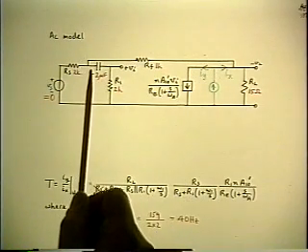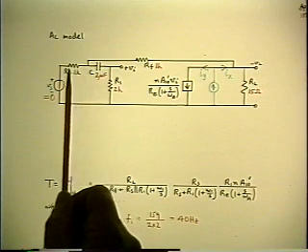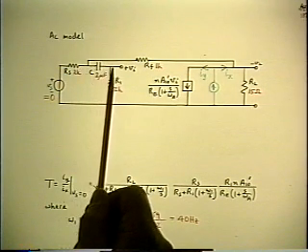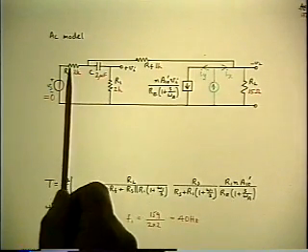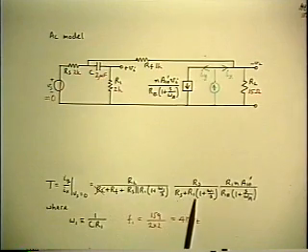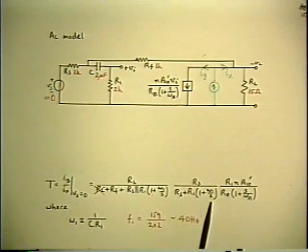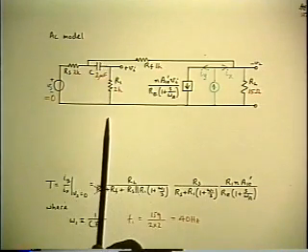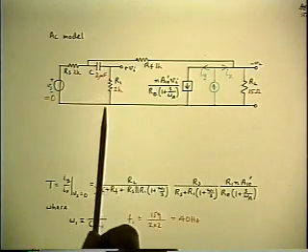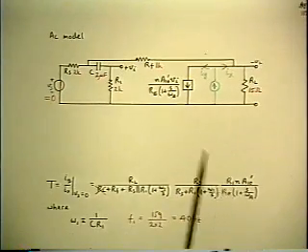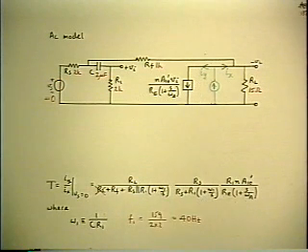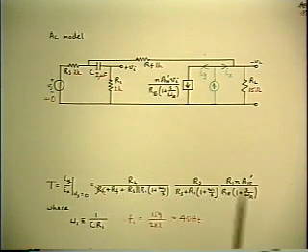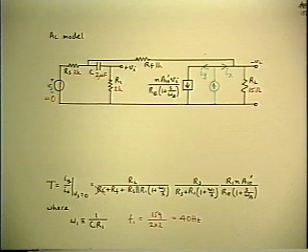The next thing I want to know is it's splitting again. I want to know how much current goes into the capacitor. Again, opposite branch RS divided by sum of branches, RS plus R1 with its corner frequency. So now we're at the current in R1. I multiply that by R1 to find VI. I multiply VI by all of this coefficient, and the result is IY. So that's everything. That's the loop gain.